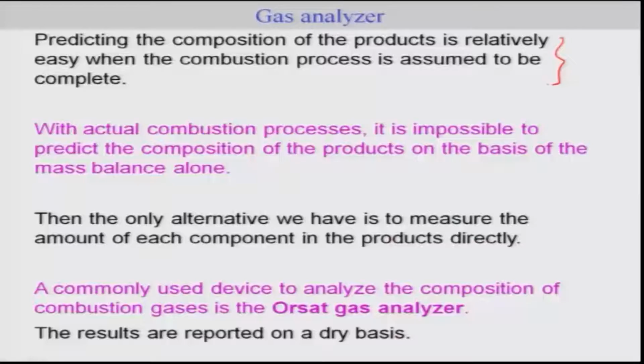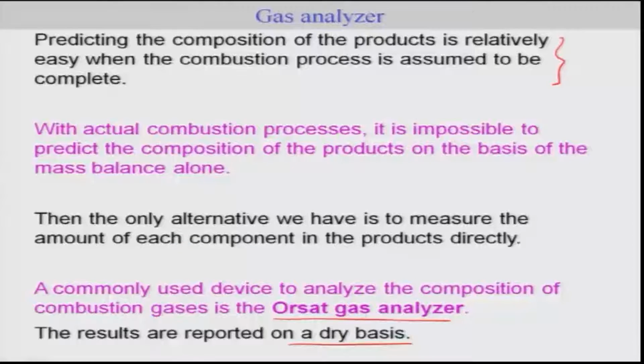This particular analysis is typically done by something called an Orsat gas analyzer, which reports on a dry basis. That means the water is not considered in the analysis. That's the meaning of dry basis. So we will be assuming that the composition we have been given is through an Orsat gas analyzer in general. Whether it's a dry basis or wet basis is something which will be provided to us. So this is an example.